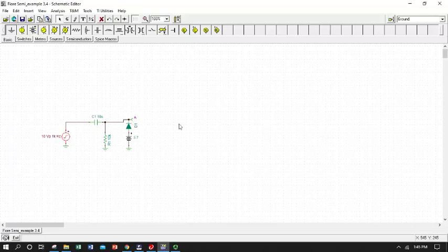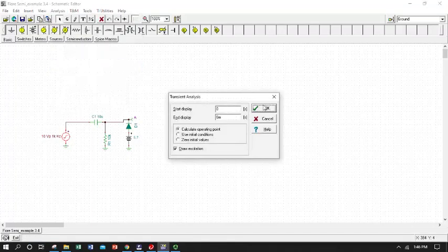So we have to remember that when we have voltage sources connected in parallel at a single node, we're going to default to the highest one at any given time. So let's see what that looks like with our analysis. We're going to take, again, about a period and a half of time.